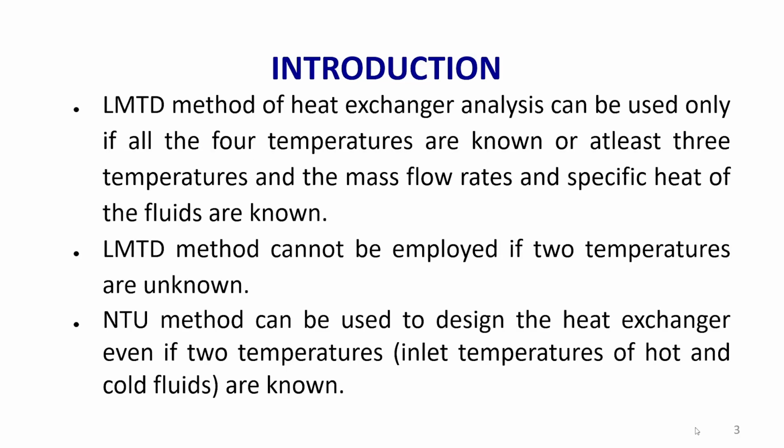If we have a look at the LMTD method, to find out the LMTD of a heat exchanger, irrespective of the direction of flow, whether it is parallel flow or counter flow, we should know all 4 temperatures, that is the inlet temperatures of both hot and cold fluid and the outlet temperatures of both hot and cold fluid. Unless we know all 4 temperatures, it is not possible to find the LMTD of a heat exchanger. So, this is a very simple, very easy method, and if we know all 4 temperatures, then we can find out the LMTD of parallel or counter flow.